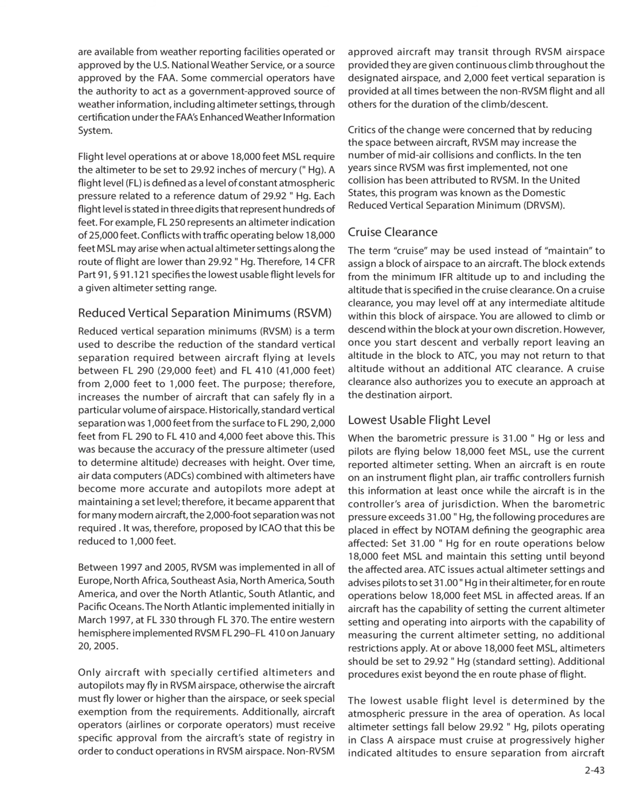reduction of the standard vertical separation required between aircraft flying at levels between FL 290, 29,000 feet, and FL 410, 41,000 feet, from 2,000 feet to 1,000 feet. The purpose, therefore, is to increase the number of aircraft that can safely fly in a particular volume of airspace. Historically, standard vertical separation was 1,000 feet from the surface to FL 290, 2,000 feet from FL 290 to FL 410 and 4,000 feet above this. This was because the accuracy of the pressure altimeter, used to determine altitude, decreases with height.